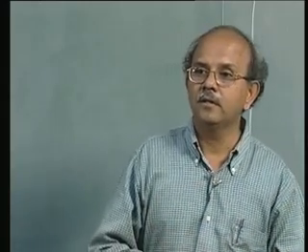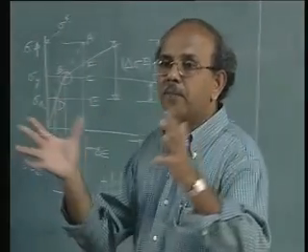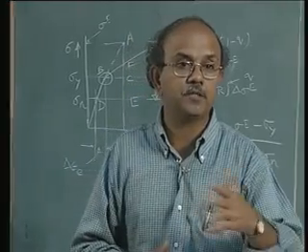In other words, there is a tug of war between two atoms. On one hand you're trying to pull them apart, on the other hand they would like to come to an equilibrium position, so you distort the lattice by applying the load. And when you release the load, the atoms come back and stay in their designated positions, the lattice positions.